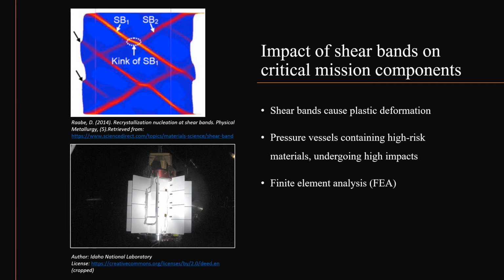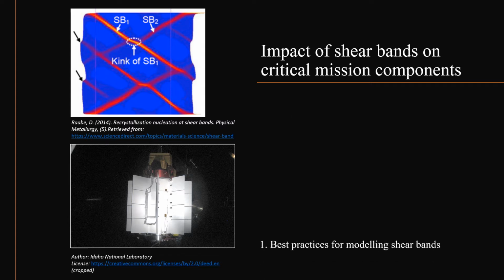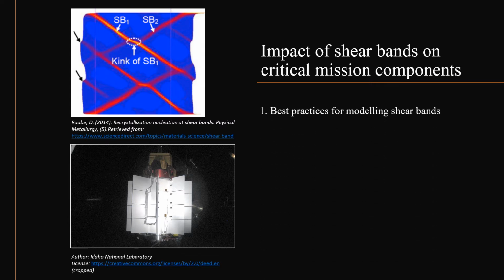Because of the safety hazards posed by physical testing, as well as these significant costs, my research will use finite element analysis, a computer-based numerical simulation in Abaqus, to gather data. Ultimately, my two main goals are to identify the best way to model shear bands, specifically in geometry similar to the radioisotope power system, and to reduce the effects of those shear bands by varying internal radius sizes.